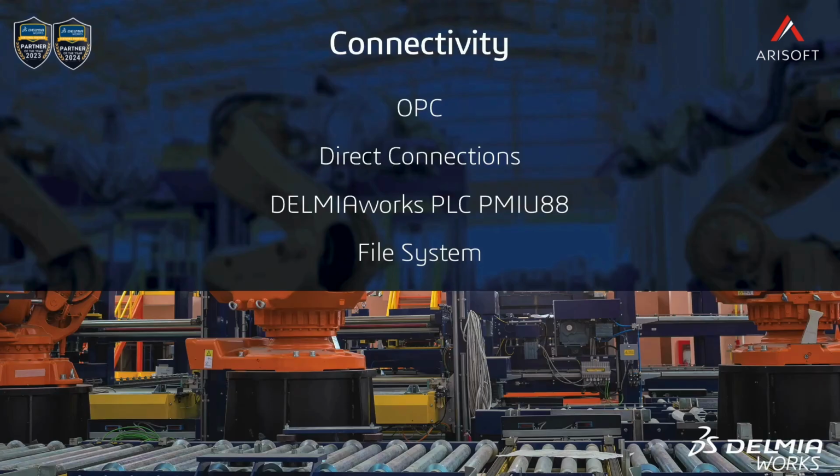Real-time process monitoring provides 4 connectivity methods to your factory floor. The first being OPC. Real-time process monitoring can connect and integrate with OPC client-server compliant systems. OPC is a client-server technology and a leading widely accepted industrial communications standard. OPC enables the exchange of data between OPC-compliant industrial field devices and applications. The OPC server is a software program that converts the hardware communication protocol used by a PLC into the OPC protocol. Most new industrial systems are OPC client-server compliant.